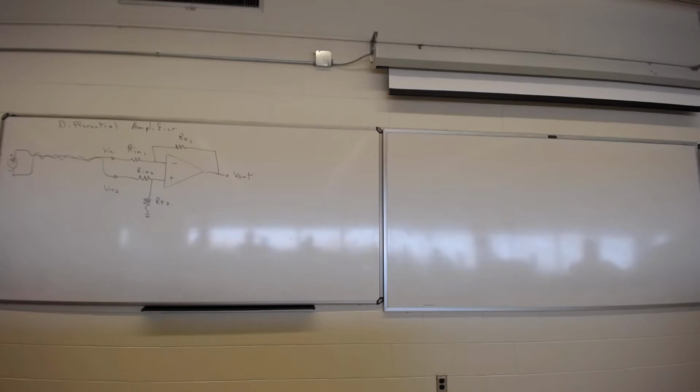Now, one of the problems with working in an industrial setting is there's a lot of radio frequency interference going on. There's a lot of electrical energy in the air, all kinds of frequencies. So what often happens is you're going to get 60 hertz, or it could be 400 hertz off a motor or switch. It could be anything. A lot of noise. So that noise, I'm going to put 60 hertz here. So a couple of 60 hertz.